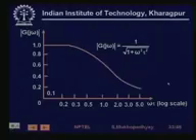On the other hand, as the input frequency increases, before the output of the instrument can really rise, the input changes. So the output can never rise enough, and therefore the gain falls. So this is the frequency characteristic of an instrument.